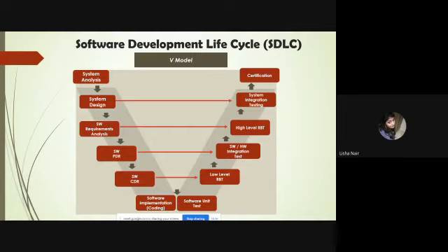Once he does the low level RBT, which is the requirement based test, he gives it to the software hardware integration tester. After the complete set of subsystems are combined into one system, this integration test happens, and then we have the high level RBT and the final system test bench.